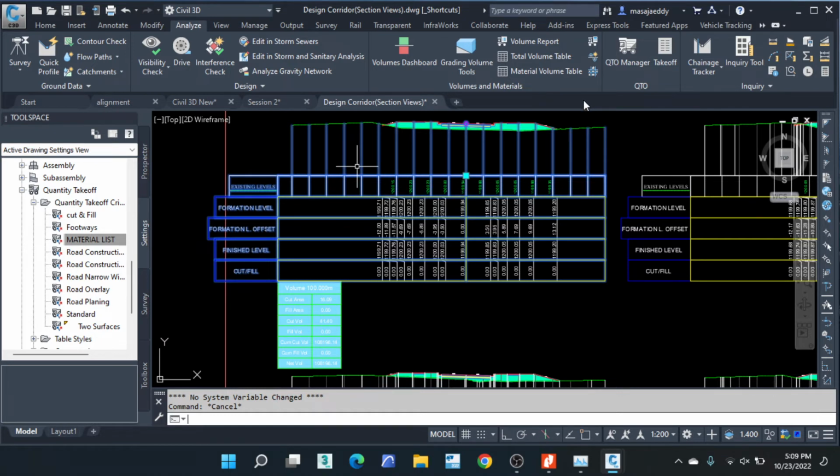That's your preference. If you want them in black and white, you can select monochrome. Then for paper size, I set it to A1, 841 by 594. It scales down to an A3 when you're printing. So I will select plot area by window.